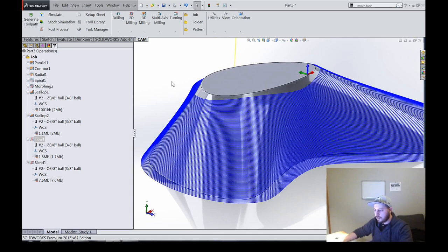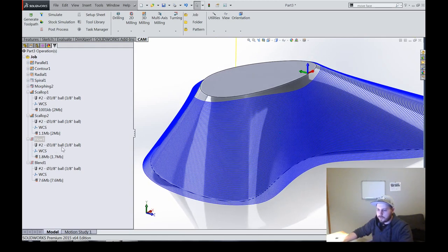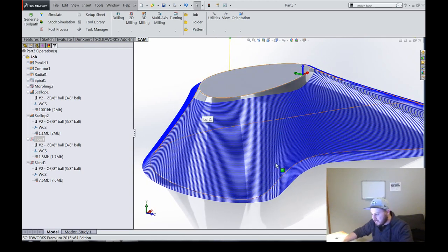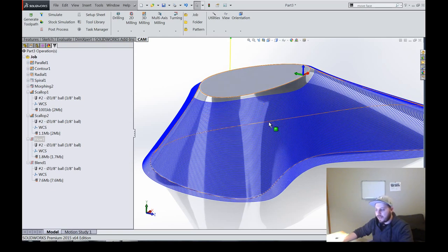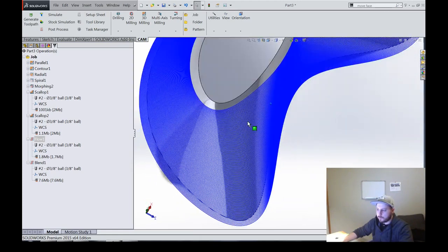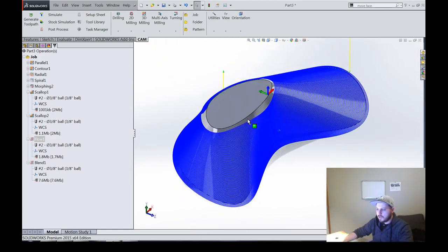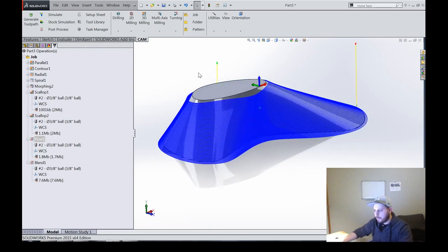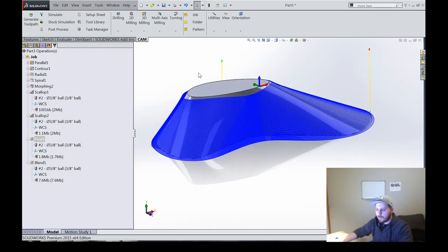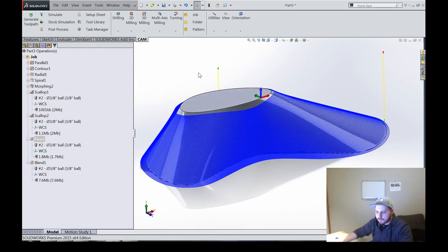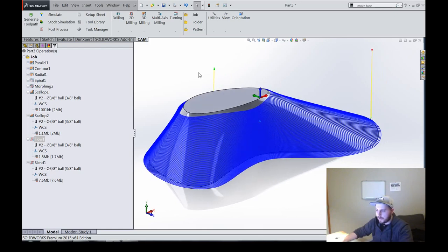It also has some underlying benefits in that it's generated based on the surface, or based on the UV vectors of the surface. Helps when you have things like undercuts and you're trying to use a lollipop cutter or 5-axis tilting in order to reach someplace that's obscured from view. If you want more on that, I did a webinar for Autodesk that went into a lot of detail on that.